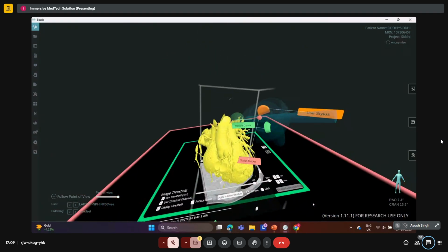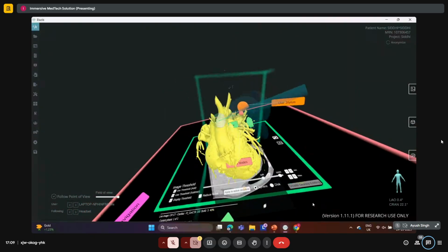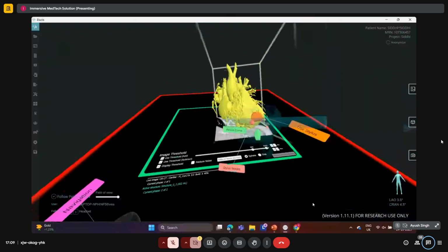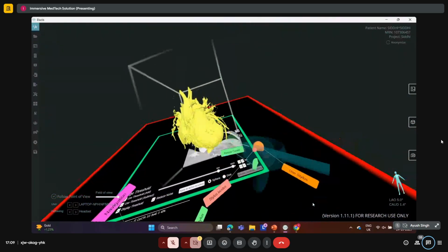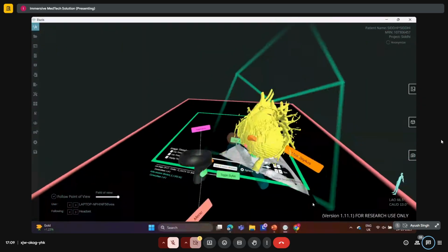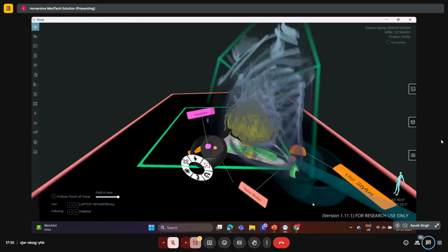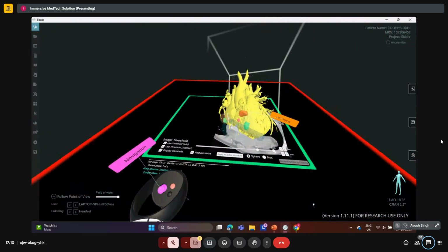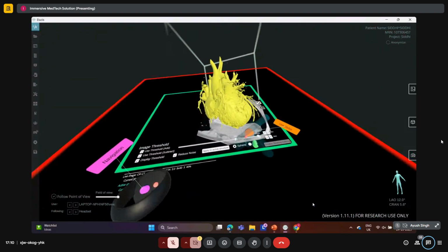And now whatever part is remaining, for example, the aorta openings, I will just click over here. This way any part can be done. And if I need to reduce the noises, I can use this single click operation. All the small noises that were present get removed. Later, the other ones that were quite large can be manually removed from here. I'll select the operation as remove, and select the threshold size.